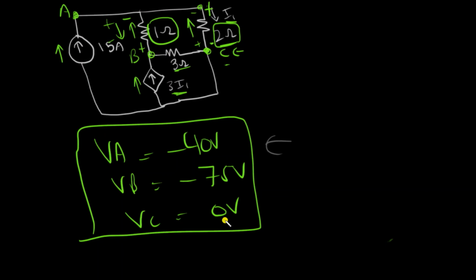So whenever you are dealing with dependent sources, just write down the simple KCLs for each node except the reference node, and for the last equation, just link the quantity that the sources are dependent on with something related to nodes. So that is how you can get to the answer. And I hope this makes things a little more clear about how to use nodal analysis with dependent current sources involved.